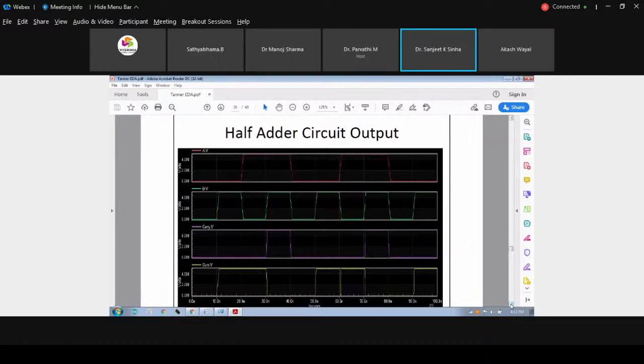When we have 1, 0, in this case also we get 1 as output and there is no carry. But in the fourth one, if we have 1, 1, then we get 0 as the sum, and in that case we have a carry. So this is the simple justification, through which you can justify that your circuit is 100% right.